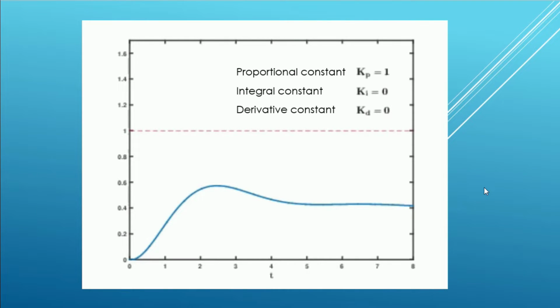First, let's understand what PID control is. PID stands for proportional, integral, and derivative control. In our demonstration today, there are three control outputs that will work together to maintain a desired temperature by reading a 13-bit I2C temperature sensor and adjusting a heater's power output using pulse width modulation. Let's take each of the control methods and see how they work together.